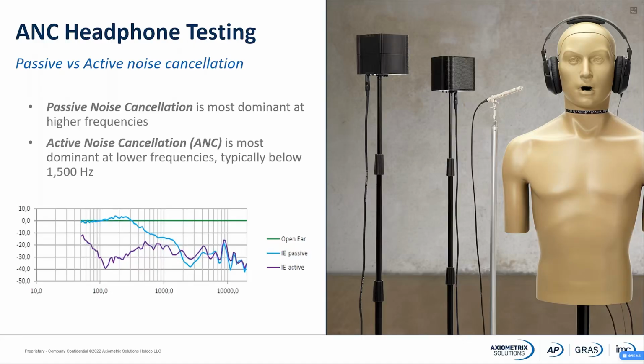Regarding testing for ANC, how representative is pink noise for real-world situations? Well, I definitely wouldn't send a device to the market by using only a pink noise signal nowadays. There are so many other things to consider, where the thing is that if we only use pink noise, then we really don't know how the headset or the ANC algorithm is going to behave in more realistic environments. It's not very common to find pink noise in realistic situations.